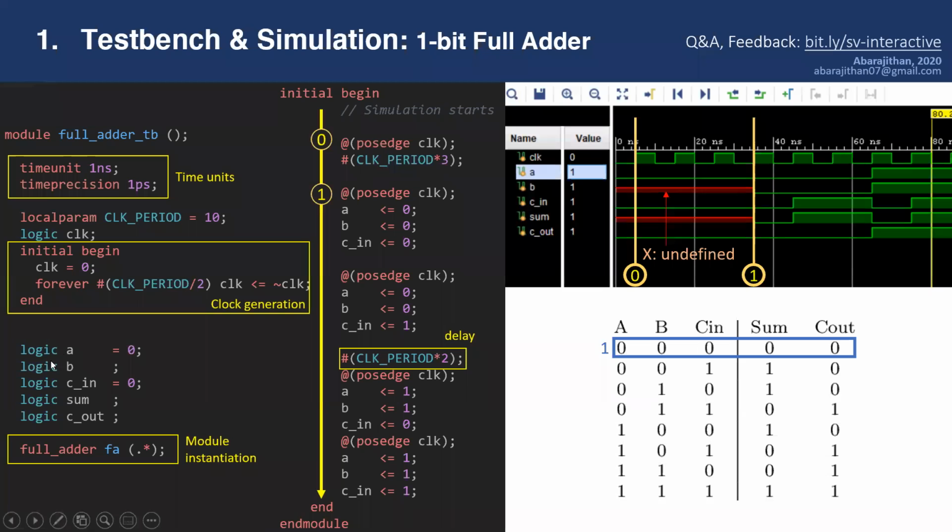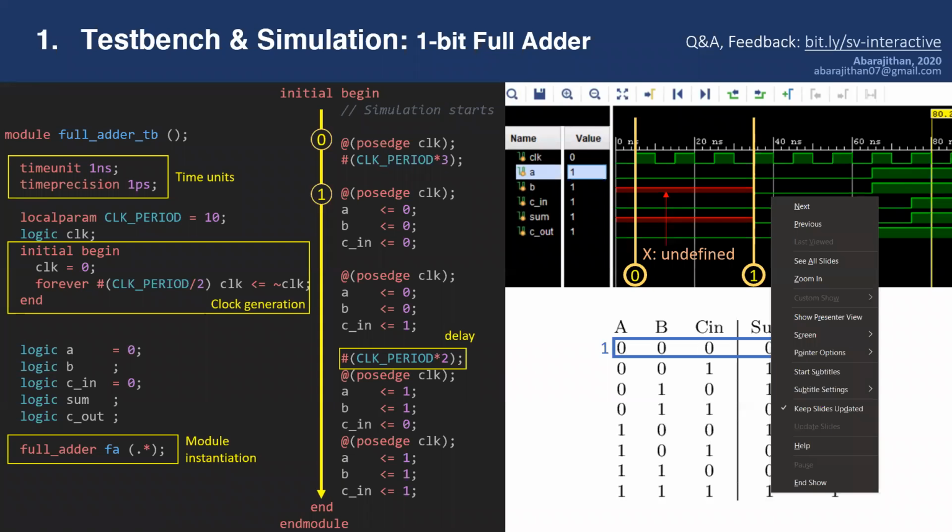Then there is another one called the bit type. If you use bit, it can take only two values, either zeros or ones. The advantage of using logic is you can find mistakes in your RTL design very easily. Inside the RTL code, if you don't connect a wire somewhere, if you just leave a wire hanging, you will get a blue line here. Or if you make a mistake and assign two things to the same wire, you will get a red line here.